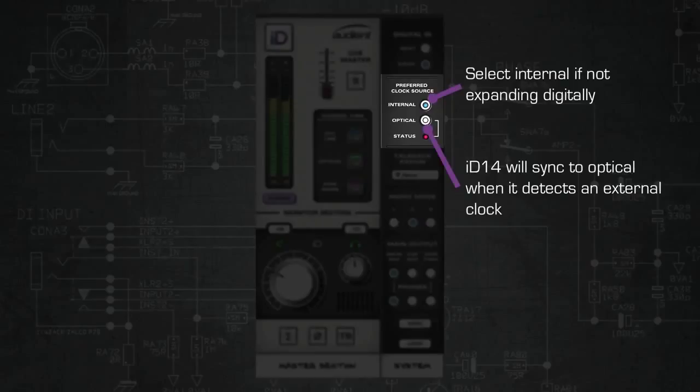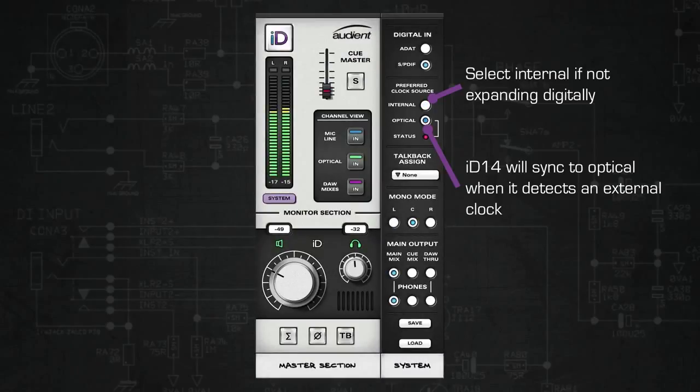Underneath we have the preferred clock source. If you have a piece of gear hooked up to the digital input, then you'll want to have it set to optical, so you can make the iD14 the slave. If you have it set to optical, iD14 will search for a clock signal on the optical input, and if it doesn't find one, it will just revert back to the internal clock.